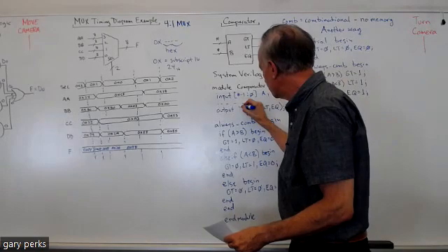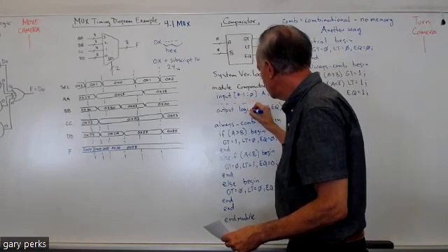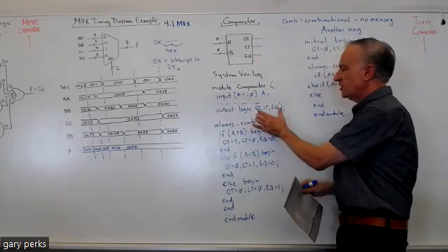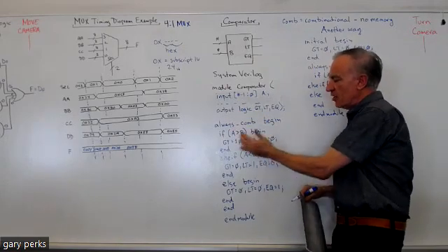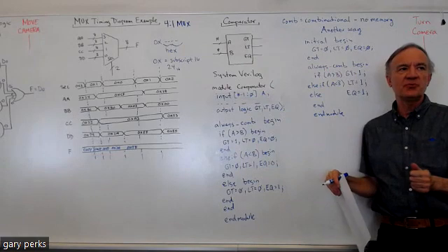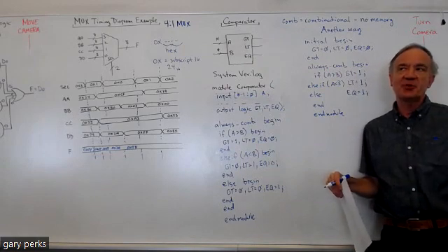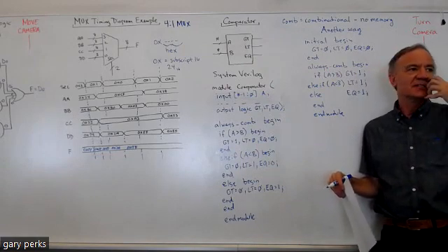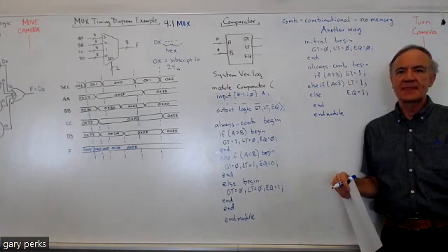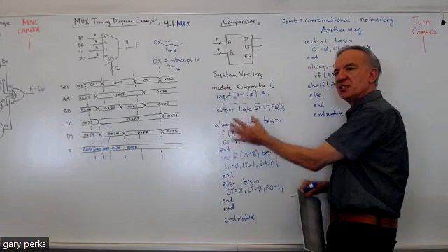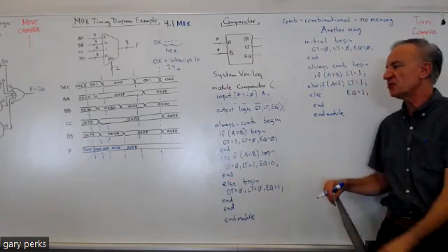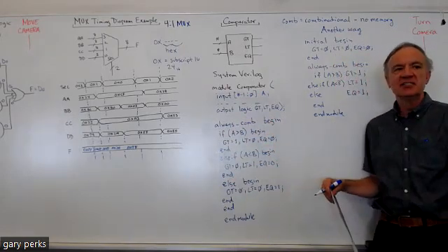You have to put logic in between output and the names of the output. You only have to do this when your outputs are within an always_comb block or an always_ff block that we're going to get to in a few weeks. You haven't been doing this previously because you weren't doing an always_comb, right? If you don't have an always_comb, you don't have to do that.